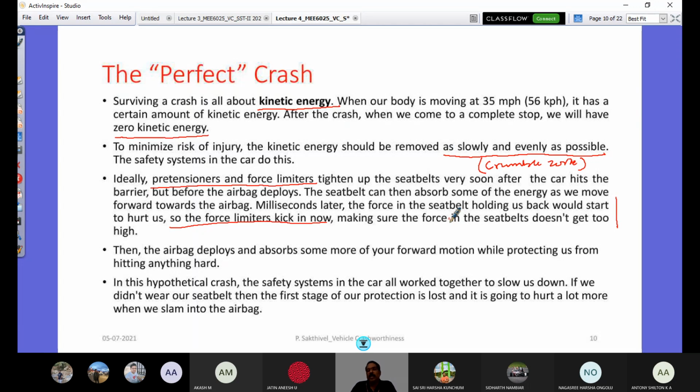So the airbag is a soft bag that can take away this energy. It prevents hard hitting of the head on the steering column. And it has to deploy at exactly the right time. So an important purpose of this crash test is to check that these passive restraints, seat belts and airbag, are deployed at the right time. So how do you identify that? The acceleration and the test sensor data would reflect their functioning at the appropriate time, right?